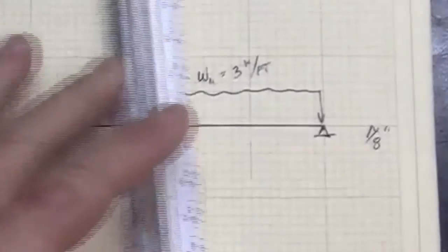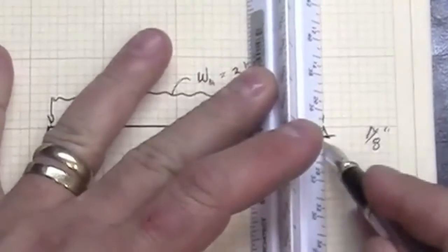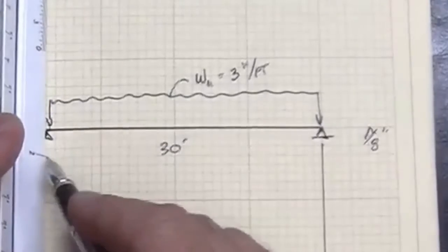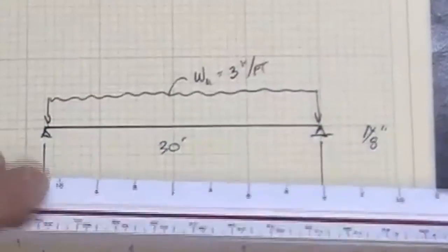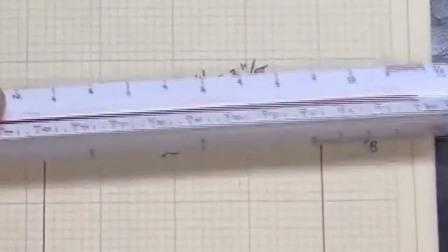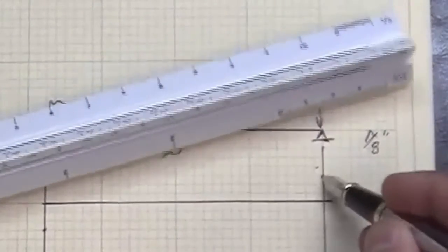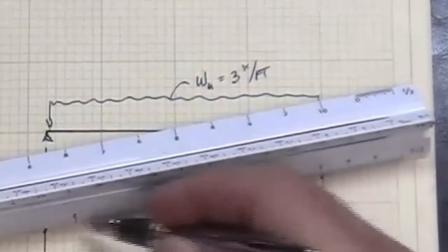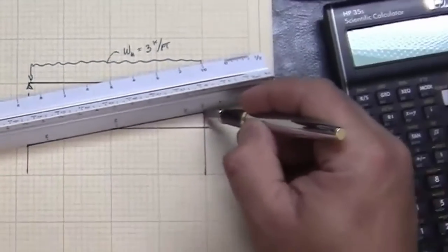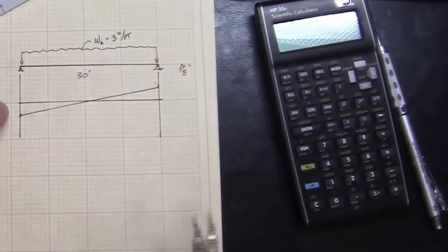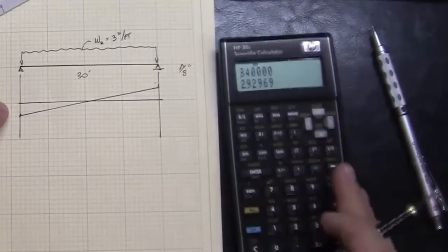Then what that would coincide with is a shear diagram that we would pick up. Shear for the member design could be D away from the supports. Right now I'm just going to work off centerline numbers for a quick estimate.